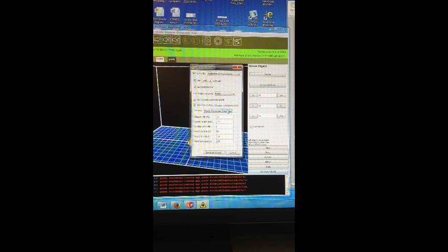Next, you will want to select the Default tab. For our projects, we'll most likely be using low accelerated defaults. Select. Next, we will select the Plastic tab, and the filament diameter is specified on the spool of material that you are using. You will want to make sure this is correct.